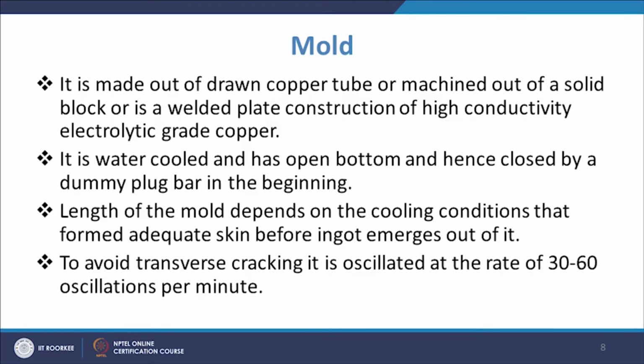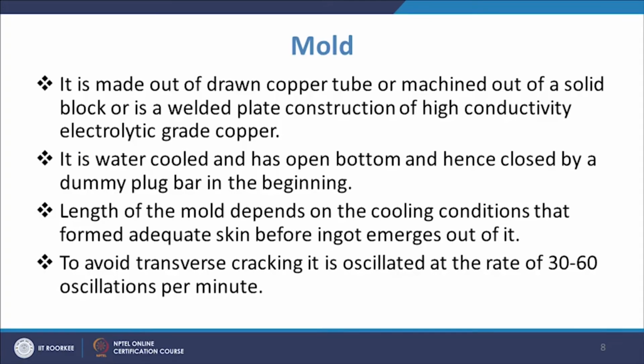Length of the mold depends on the cooling conditions that form an adequate skin before the ingot emerges out of it. So this is very important: what should be the length of the mold will depend upon the cooling conditions. The cooling conditions have to be such that an adequate skin is formed before the ingot emerges out of it.